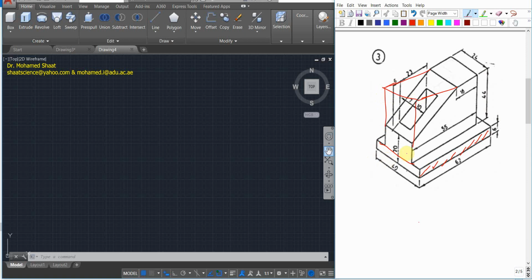In this way, we don't have a base, so we're gonna build the base here. Then we're gonna have this entire face. Then I'm gonna extend it with the 24. Then I'm going to subtract this inclined surface to end up with the inclined surface. Then I'm going to subtract the top, right? We can do the same, but this is gonna be further more steps, right? Because you're gonna add one more subtraction to create this inclined surface.